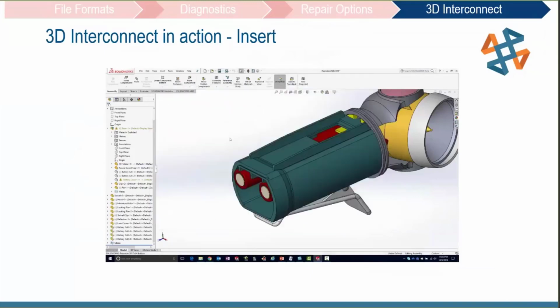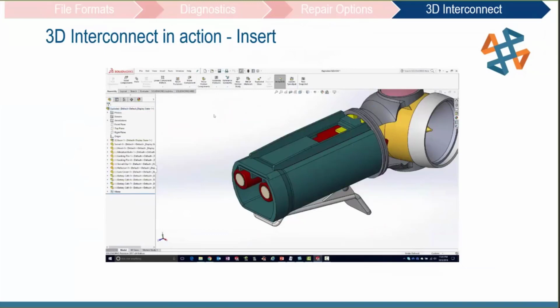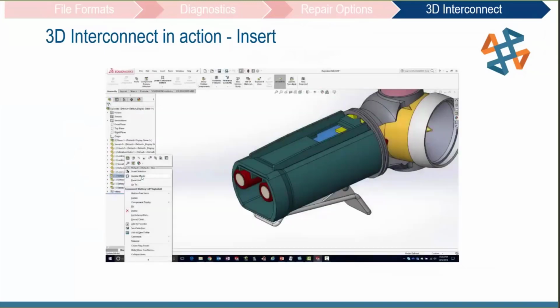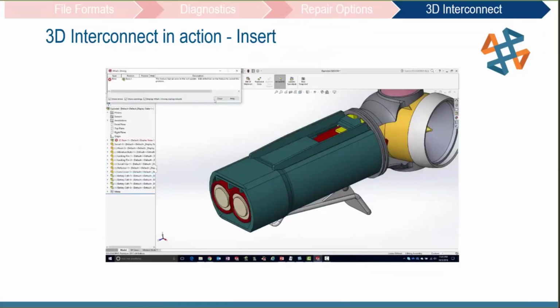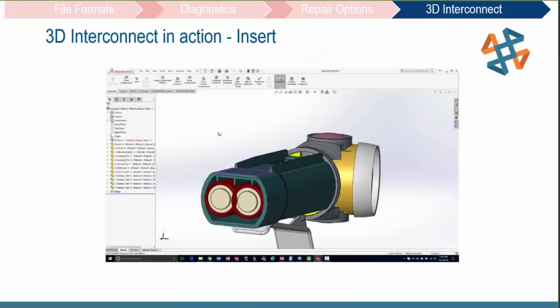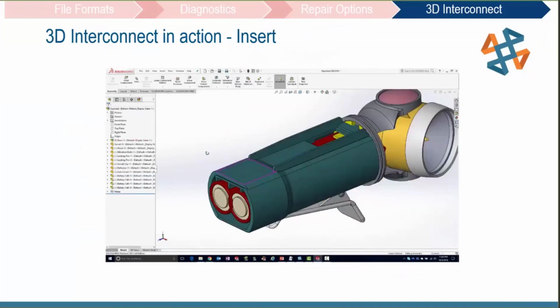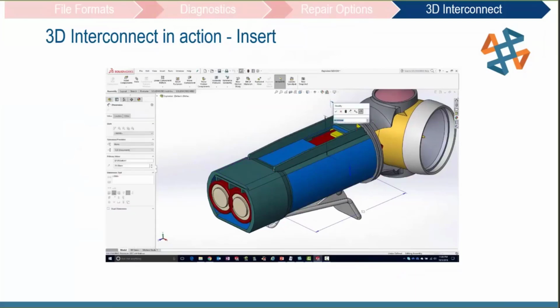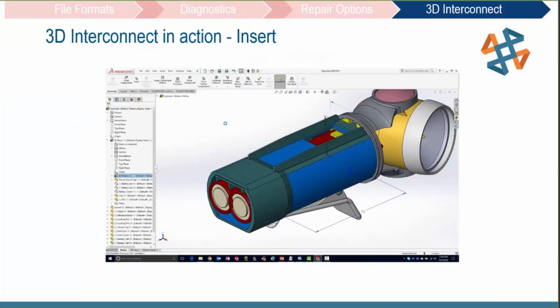So I replace it. I go back to my model. I can rebuild it. But now the symbols in the tree, right, it still shows that it's linked to the external file. I can right-click it, and there's Update Model. So that is basically reloading. And look at that. So it's a new version of the battery, larger diameter, longer length, and the housing updated because of that reference, because of that up to surface. So it's not necessarily just a dumb solid anymore. It's maintaining that reference. So fixing a few other geometry issues here.